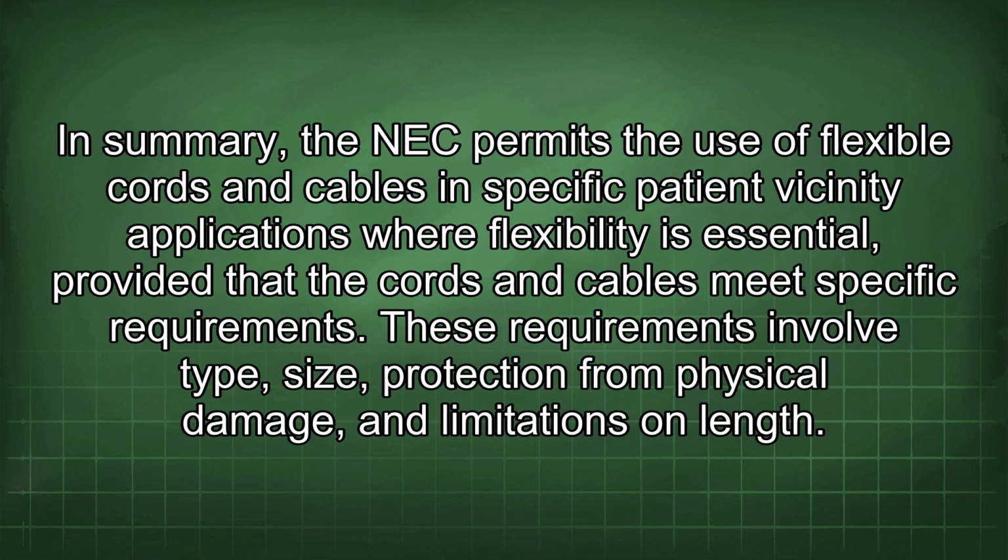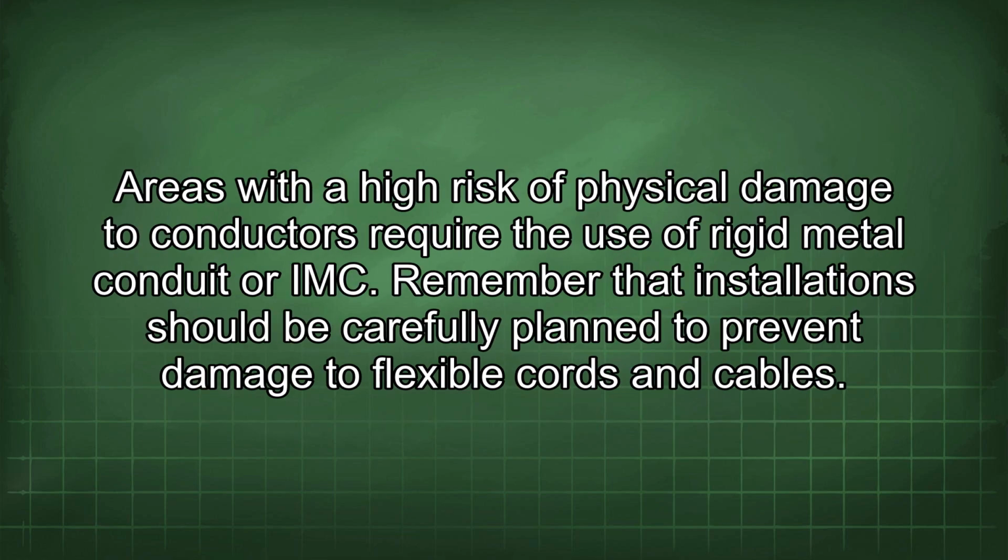In summary, the NEC permits the use of flexible cords and cables in specific patient vicinity applications where flexibility is essential, provided that the cords and cables meet specific requirements. These requirements involve type, size, protection from physical damage, and limitations on length. Areas with a high risk of physical damage to conductors require the use of rigid metal conduit or IMC. Remember that installations should be carefully planned to prevent damage to flexible cords and cables.